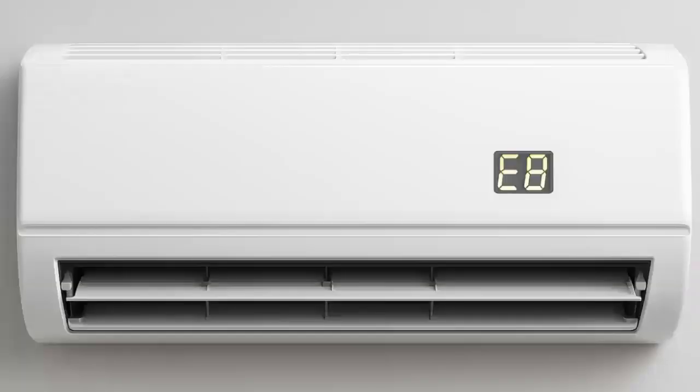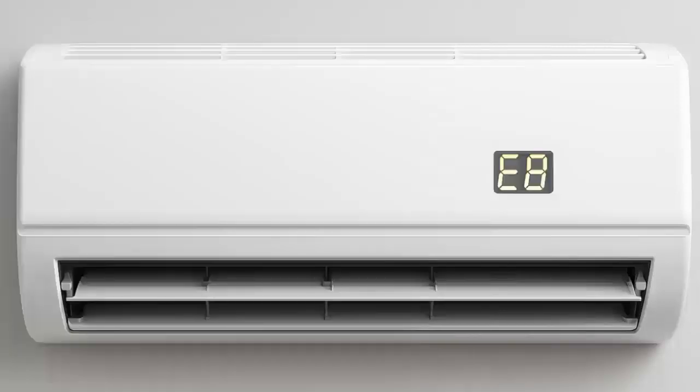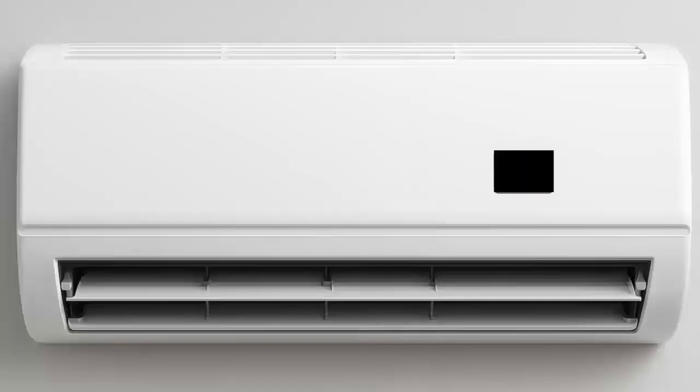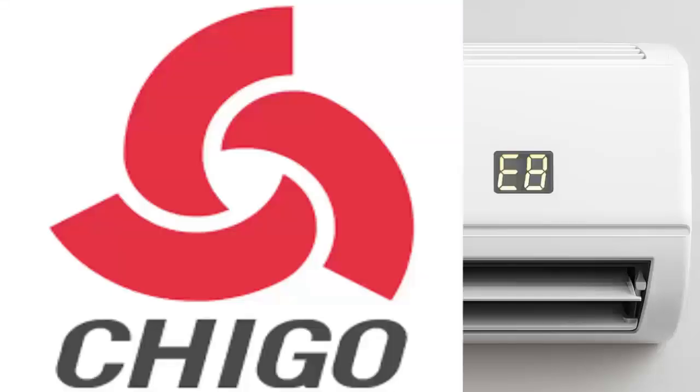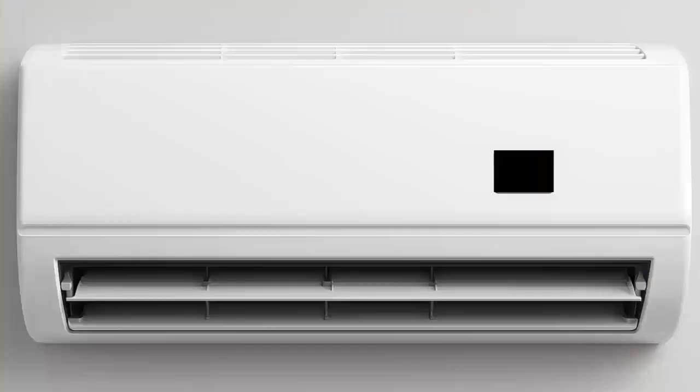B. E8 error due to evaporator thermal faults, overheating or freezing. In some brands, E8 is related to temperature issues in the evaporator, either due to overheating in heating mode or freezing in cooling mode. Brands where this occurs: Mitsubishi, overheating in heating mode. Chigo, thermal protection due to excessive temperature. Possible solutions. Check the condition of sensors and the indoor coil. Ensure the fan is working properly. Check for airflow obstructions.